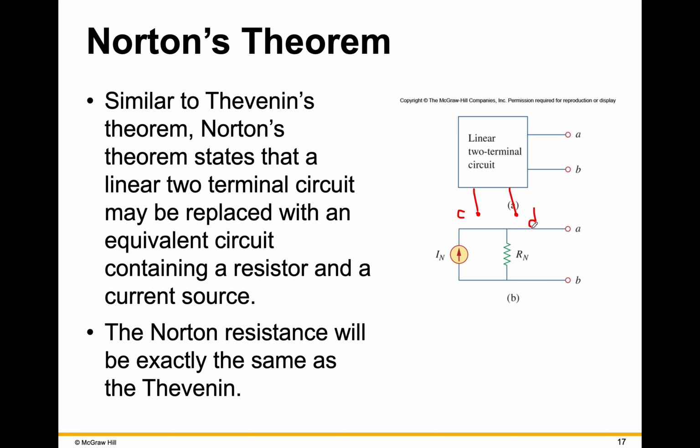So the Thevenin equivalent circuit is highly dependent on where you take your output. If you move your terminals and take your output at a different location, then you're finding a different Thevenin equivalent. This is one of the biggest problems that I observe students have in finding Thevenin equivalents, particularly when finding the open circuit voltage. They'll find a voltage somewhere else in the circuit, or they will try to simplify the circuit too much to find the voltage.